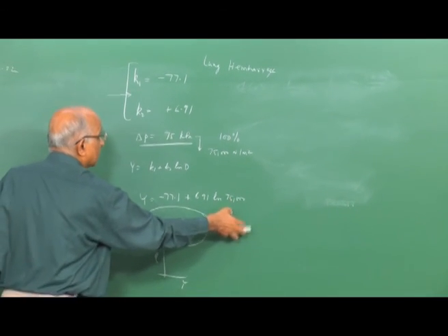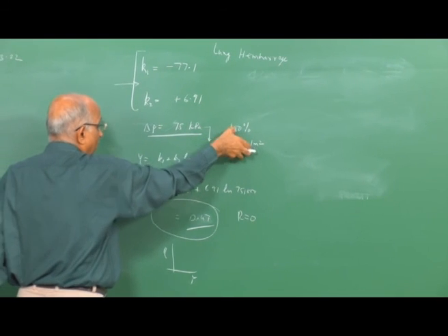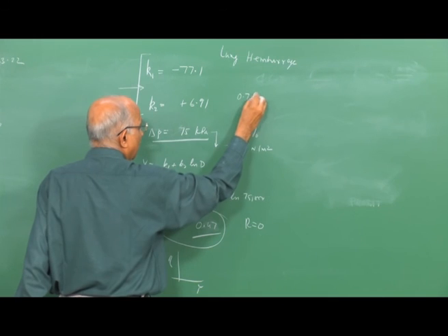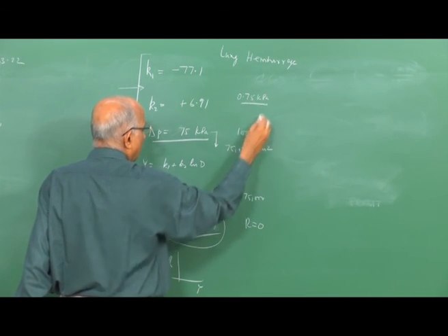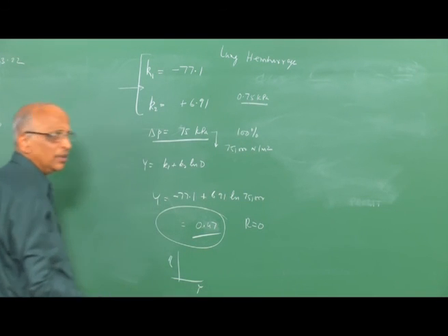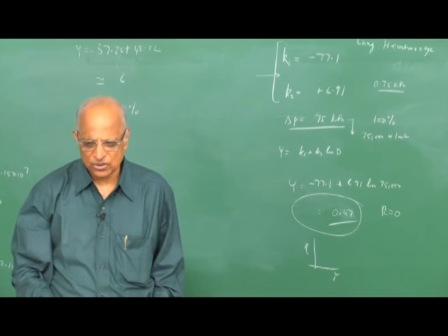That means nobody's lungs get ruptured, but since my overpressures are very large compared to something like 0.75 kPa to rupture a window pane, I have something like 75,000, well, all the window panes get ruptured. This is how we do problems involving quantification of damages.